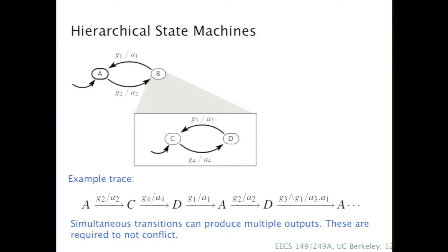Okay? Yes, Gil. Setting variables. So that's a really tricky one, right? And you have to be careful. And this is where a lot of state machine formalisms don't get it right. Okay? In our formalism, the set actions are distinct from the output actions. Okay? And the set actions are all performed after the reaction has been concluded. Okay?